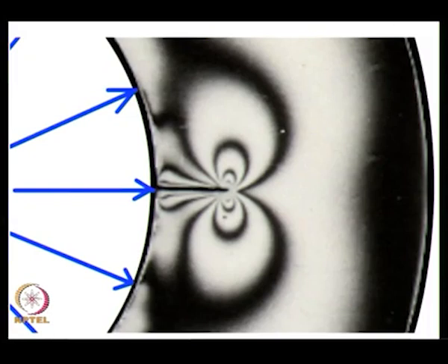the near vicinity of the crack tip, and in this you find several geometric features which really give you a clue for you to incorporate how many terms in your analytical expression need to be used to extract and process data from the experiment to calculate the stress intensity factor.